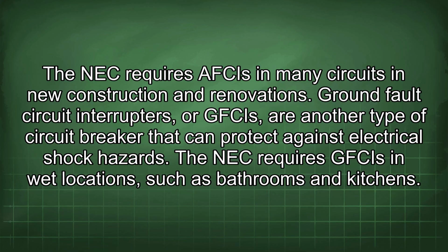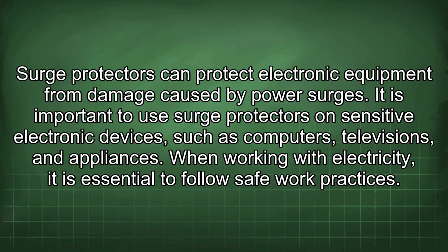Ground fault circuit interrupters, or GFCIs, are another type of circuit breaker that can protect against electrical shock hazards. The NEC requires GFCIs in wet locations, such as bathrooms and kitchens. Surge protectors can protect electronic equipment from damage caused by power surges. It is important to use surge protectors on sensitive electronic devices such as computers, televisions, and appliances.